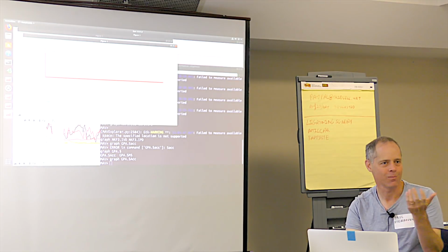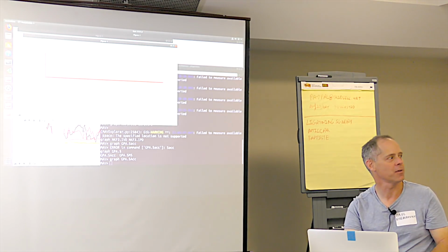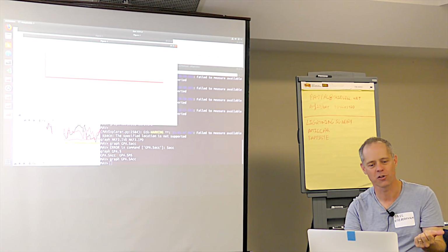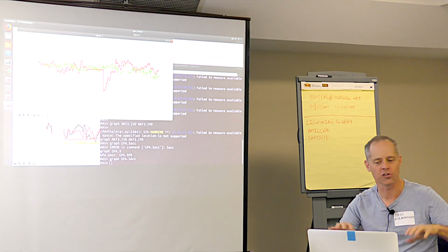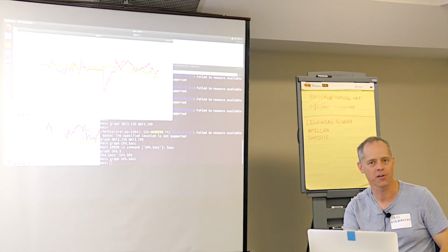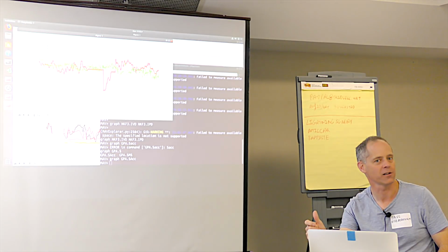Look at that. So, see, not all of our GPSs produce that data. U-blox do, but other drivers don't, unfortunately. You might be able to infer it by looking at the position, but that's usually a reported position accuracy, and that's pretty lagged. But in terms of just looking at the data rather than what the GPS says it's doing, I say, well, hang on a bit. Here, the GPS jumped by 6 meters per second for a short period of time. Now, that's a caution in a flight because if the GPS has done it once, can it do it again? So now immediately the GPS is on the suspect list.